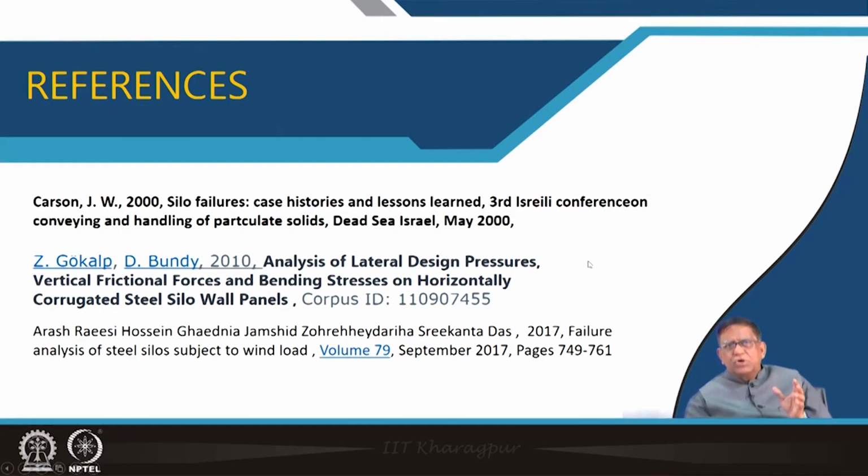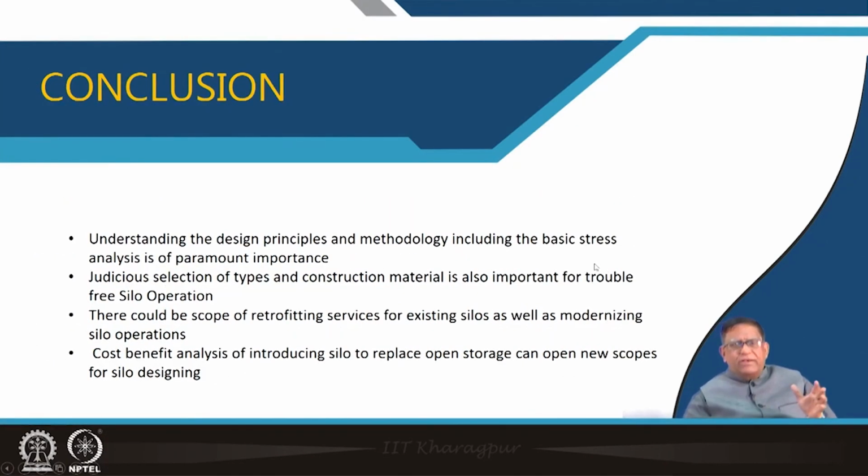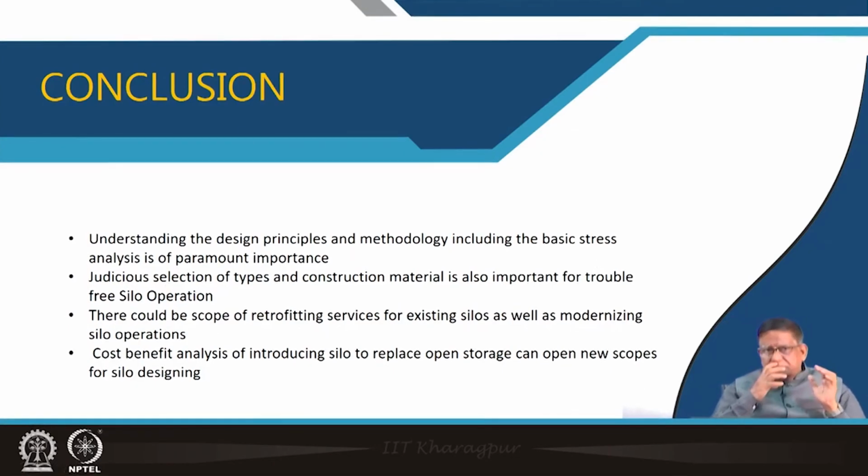So, I request you to go through these articles, and then you will understand that the design principle and methodology, which includes basic stress analysis, is of paramount importance. We will try to see how the stress analysis of a silo can be done, and then the judicious selection of construction material is also important for trouble-free silo operations. If you want to avoid failure, you need the right type of silo for the right type of material.